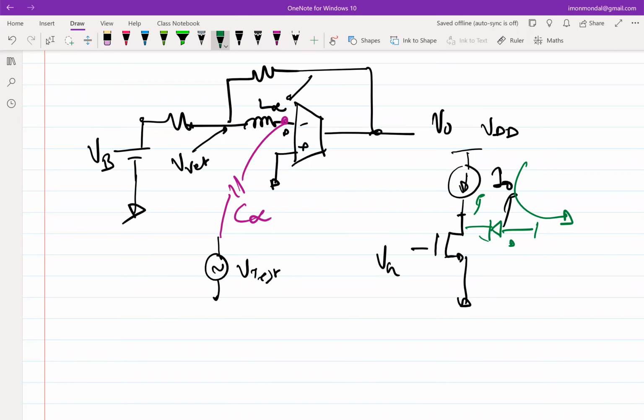Okay, so, no, right? So you will never reach that DC operating condition, right? So maybe if I put this, it will make the point clear. So you have capacitance here, right? Maybe this is CdB. So when you turn on your current source, it will take some time for the circuit to saturate, right? So when you turn on everything, what is tending to happen? The voltage across this CdB capacitance is increasing. The current is still flowing, but it is flowing into the capacitor. And you might say that the capacitor is an intrinsic part of the transistor.